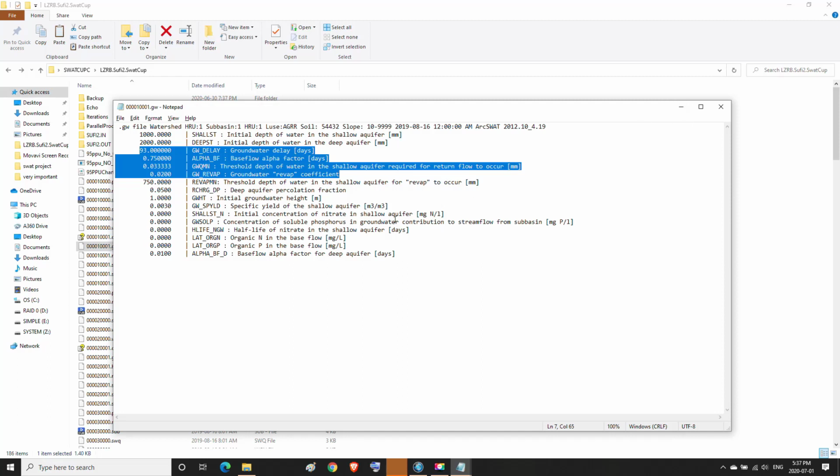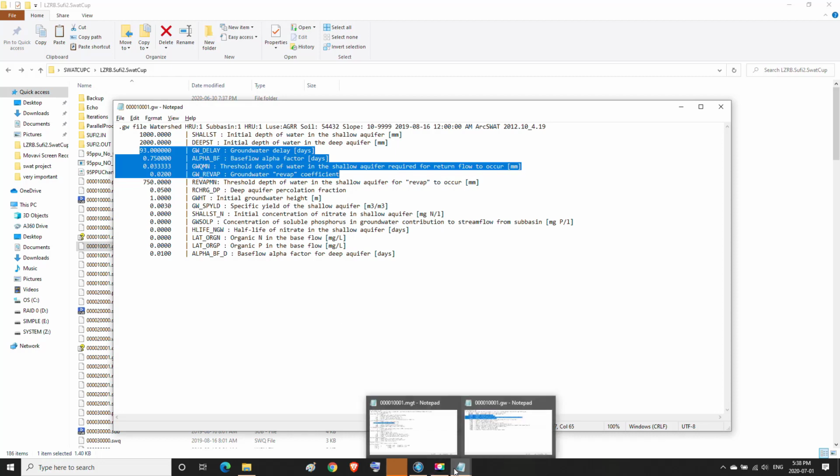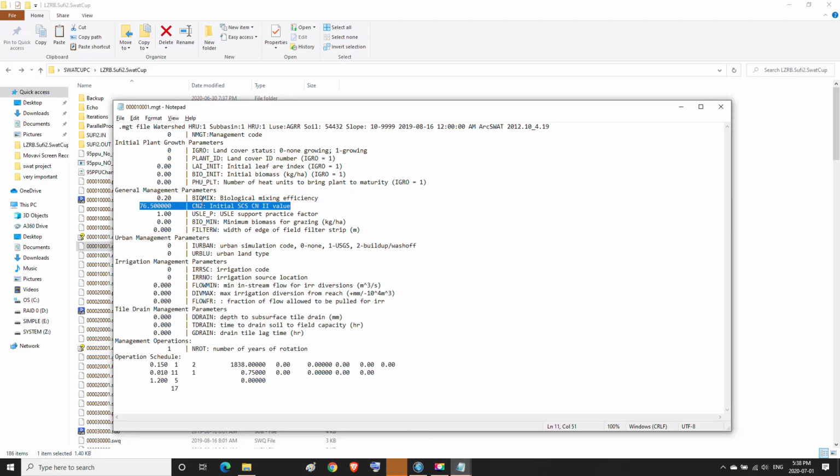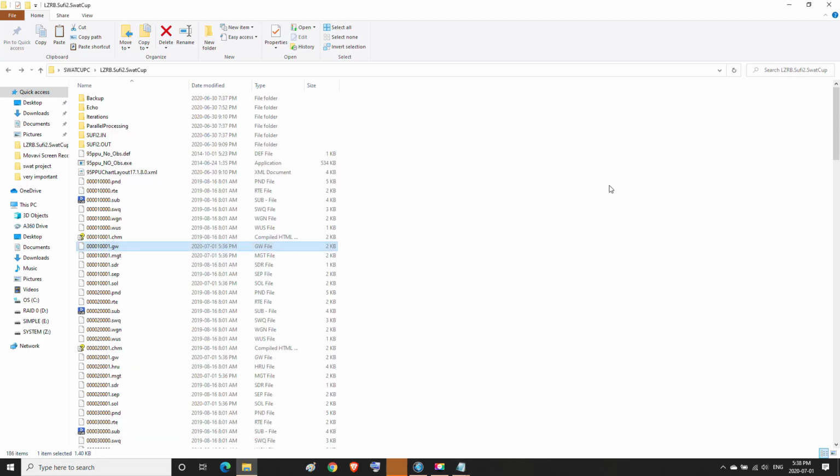And now we rewrite or enter these parameters and curve number CN2 again in ArcSWAT for the study area project, thus obtaining a certified daily discharge data that simulates the reality according to this calibration.